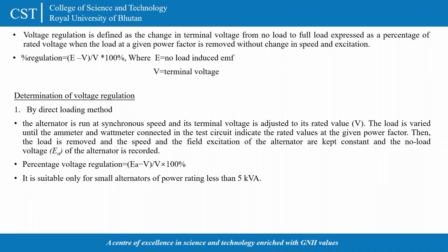Voltage regulation is defined as the change in terminal voltage from no load to full load, expressed as a percentage of rated voltage, which is given by (E - V) / V × 100, where E is the no load induced EMF and V is the terminal voltage.